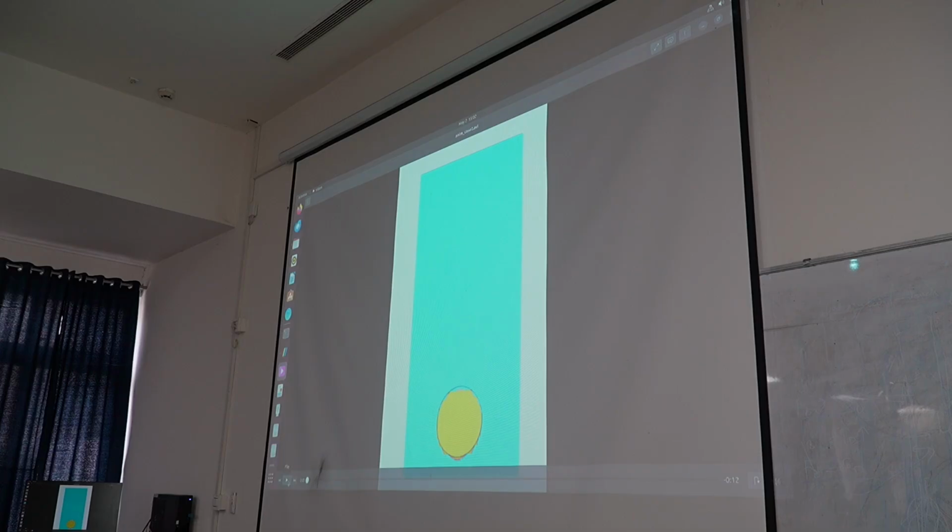And sir, you have plotted at all the times? Yes. The writing interval is 0.005, so I can only post process the files which I have written. So it's not at a specific point, you have taken all the intervals, all the points from 0.005. Yes. Only then is it able to show the initial acceleration phase and then a steady rise phase.